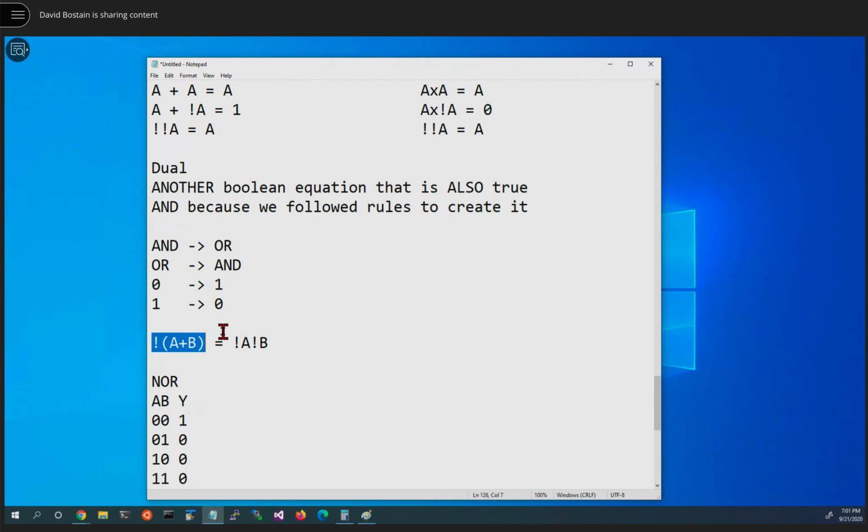They're part of what's called DeMorgan's theorem, which basically says if two things are ORed together and then inverted, that's the same as if the inputs were inverted and then ANDed. But the name of both of these functions, even though this looks like an AND, is NOR. This is called the DeMorgan NOR function. This is called the regular NOR function. There must be a dual.